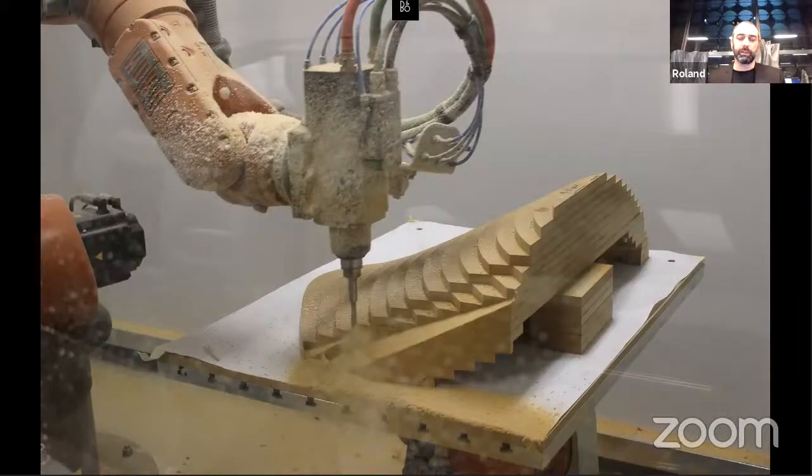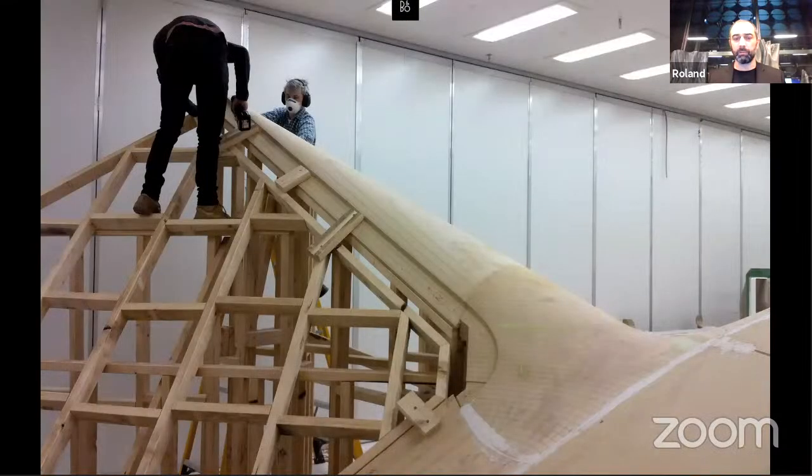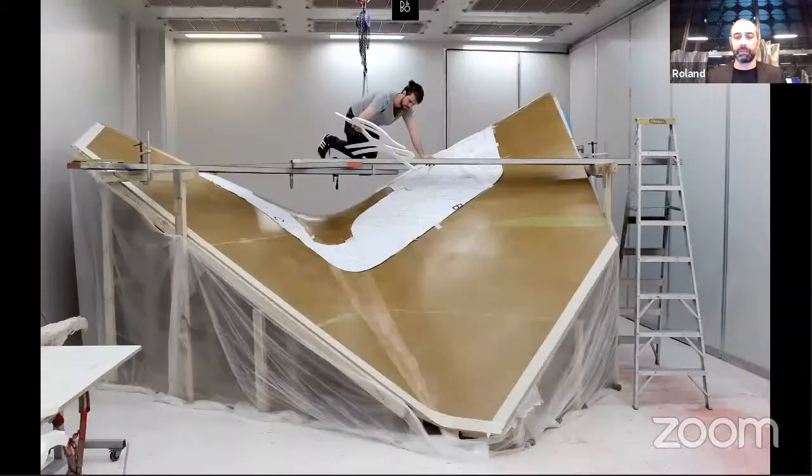The mold for the project, in the end, we used a reusable mold. So an idea that instead of trying to mill a mold for the entire project, we made one mold that could be reused to make 5 different parts, as well as several flat parts that come together to make the project. So we needed something that was more robust. So we milled parts of the project, the double curvature parts, from MDF, using robots and 3-axis gantries. And then another part of it is built by a carpenter. So in many ways, the mold becomes a small architectural project in itself.